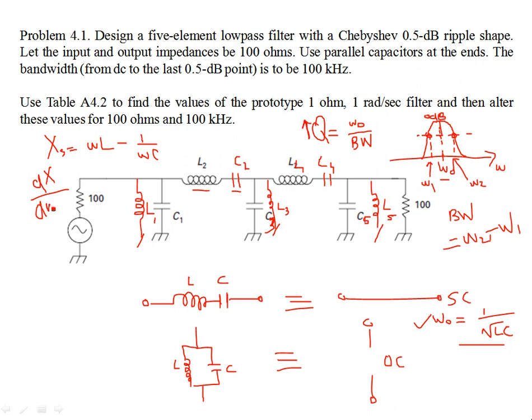This is another important thing. This just tells you the rate at which the reactance changes with respect to the frequency. This is L minus, well, omega comes up, so this becomes plus 1 over omega square C, right?